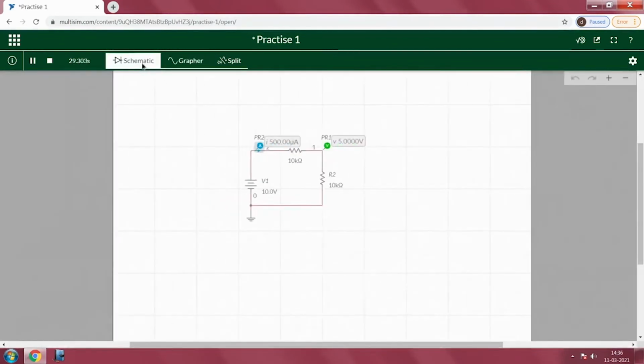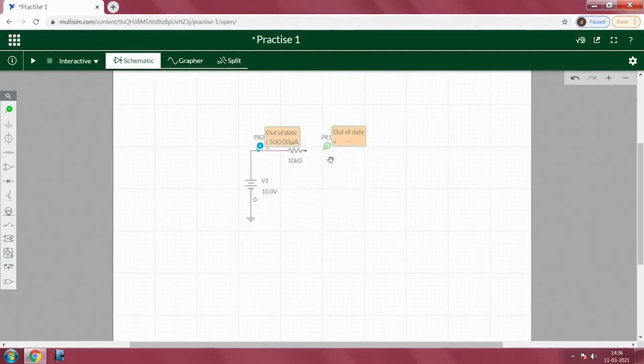Okay. So now I am planning to realize a simple RC circuit so that we can use some other mode of understanding for the simulation. So rather than taking R2 as 10 kilo ohms, I will simply delete R2. I will replace R2 with a capacitor. So it acts as a simple RC circuit, an integrating circuit or charging circuit. So 1 microfarad and 1 kilo ohm I am taking.